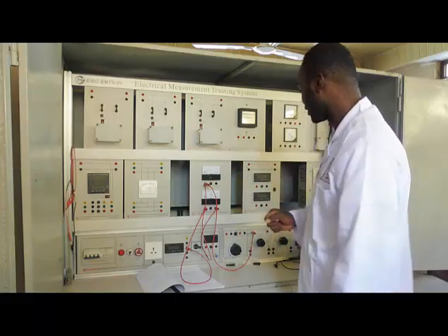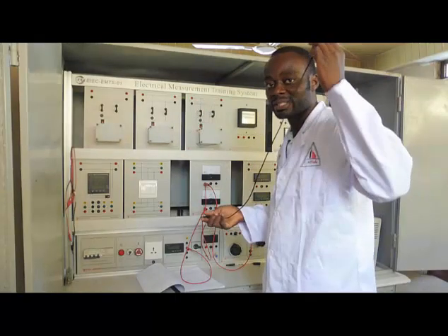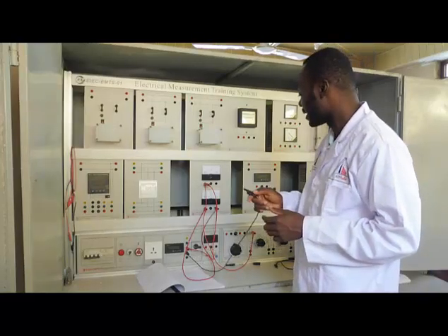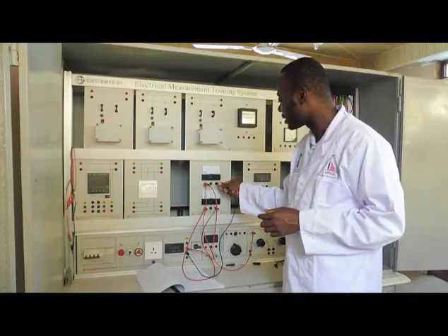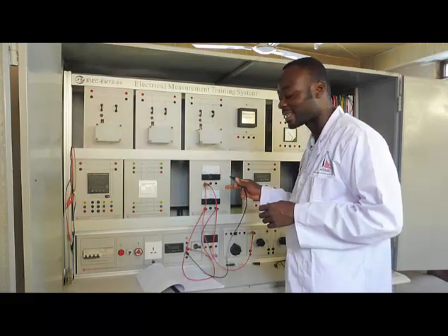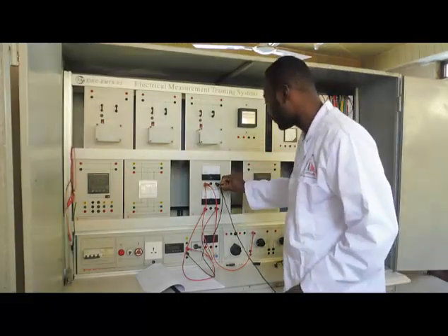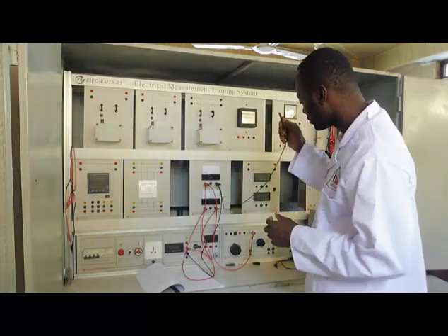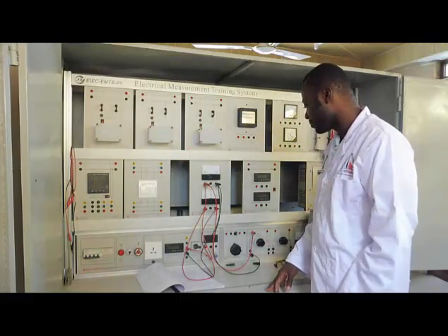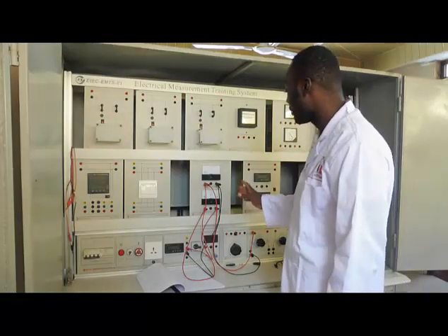So let's go to the neutral connection. I'll pick the neutral wire, which is black, and insert the neutral line. Then from there, you go straight to the voltmeter, since we don't have a neutral connection in the ammeter. Then I'll start from the voltmeter and insert it to the resistor. So now I'm done with the neutral connection, and with the analog connection.